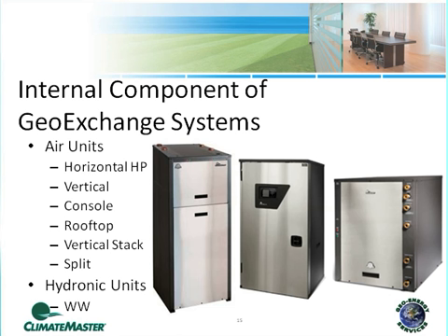All right, the final one here is what we call water-to-water heat pump units. They fit a variety of hot water and chilled water applications, and I've got 3 different styles and models shown here. These water units are typically going to be 20 or 30 or 50-ton water-to-water units, and will always have 2 compressors inside of them. And we have large projects where maybe we've got a 200-ton chilled or 200-ton hot water system.